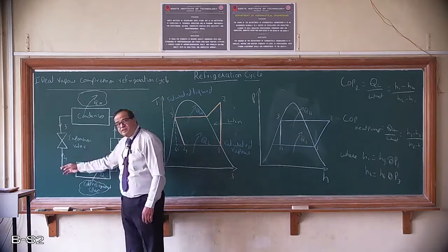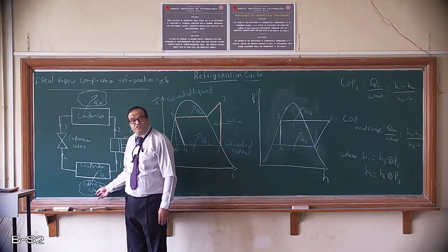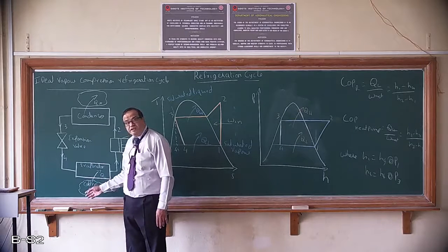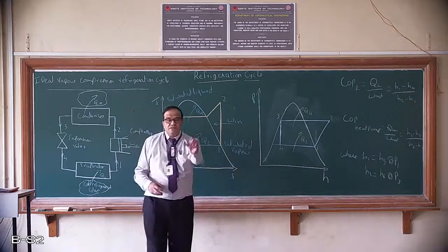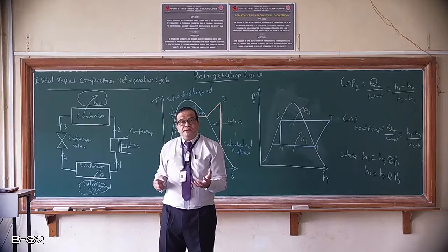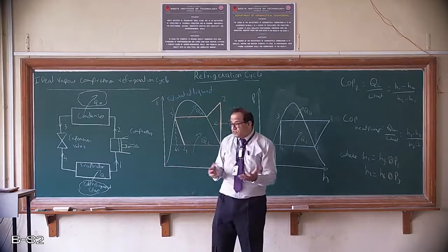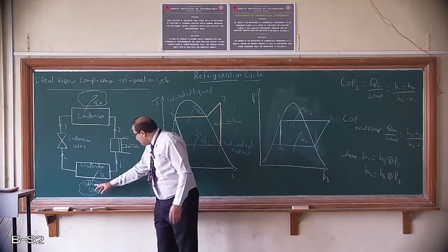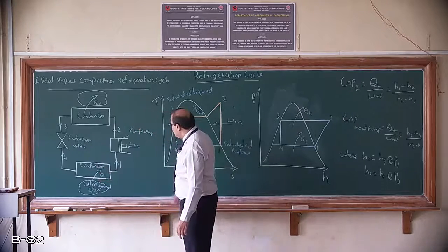The temperature of the refrigerant which enters will be somewhere around -4 to -10 degrees in an ordinary refrigerator, and then when it enters the evaporator coils, the refrigerator space will be somewhere around 0 degrees. It absorbs heat from 0 degrees. The refrigerant is at -10 degrees Celsius. So, naturally heat is transferred from the refrigerator space to the refrigerant, and then it passes out.